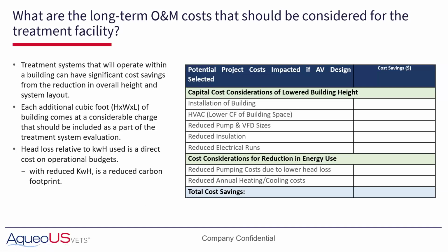This is just a quick little table that people don't take into account on the price of bid day. In some cases, these things have to be in a building. The system I just showed you there, the one in New Jersey, is actually inside. That was an existing building. The challenge there was getting the vessel in the building itself. If we went with activated carbon or even the ion exchange media, that vessel probably would not have fit in the building. We actually managed to roll that one in on pallet jacks to get it in the building. So we've got to look at that.